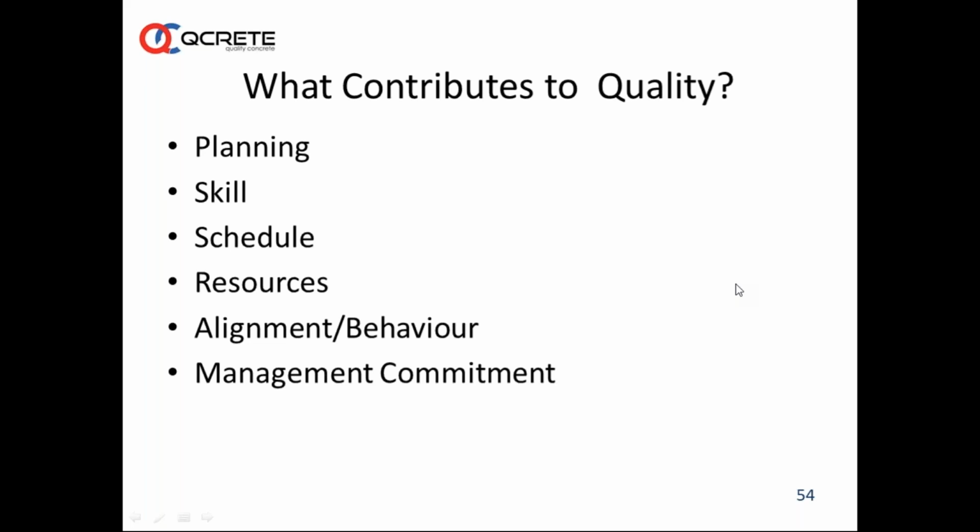Reduce the sand content if possible. Third one is also to change the admixture. Some of the admixture formulations give very high stickiness actually. So you can also change the admixture type or brand.